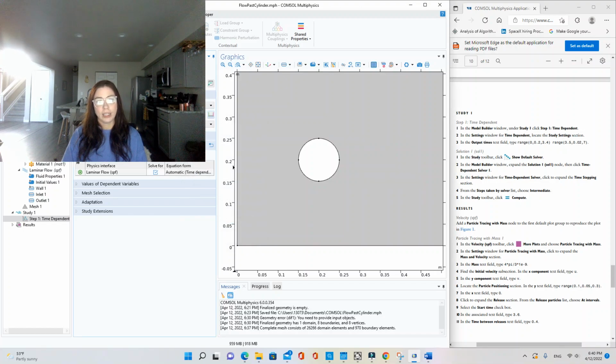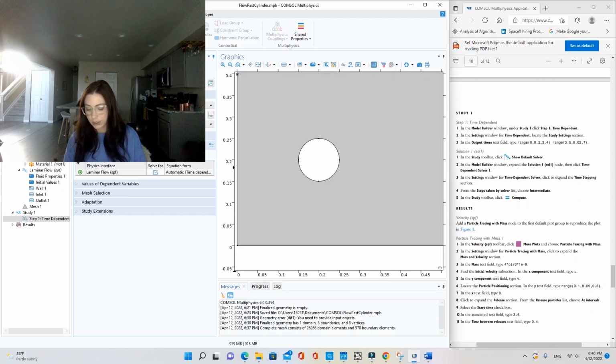So you can just click add and you'll see 2 ranges pop up. And for our second range, we're going to start at 3.5 in steps of 0.02. So we're getting finer in our increment once it hits 3.5 seconds to 7 seconds.